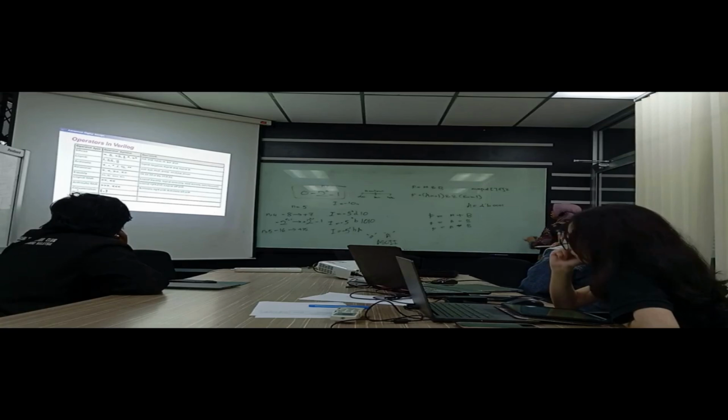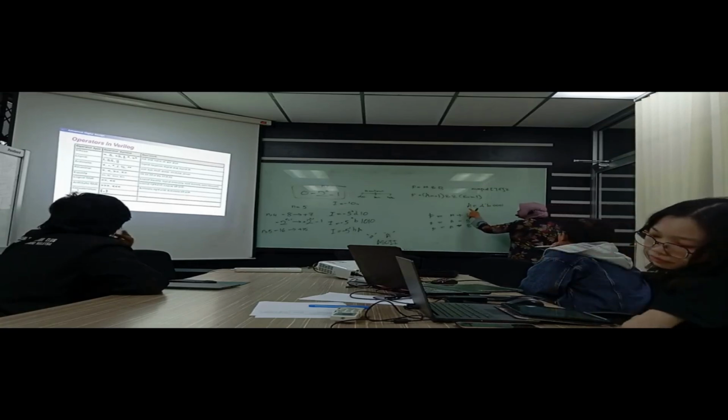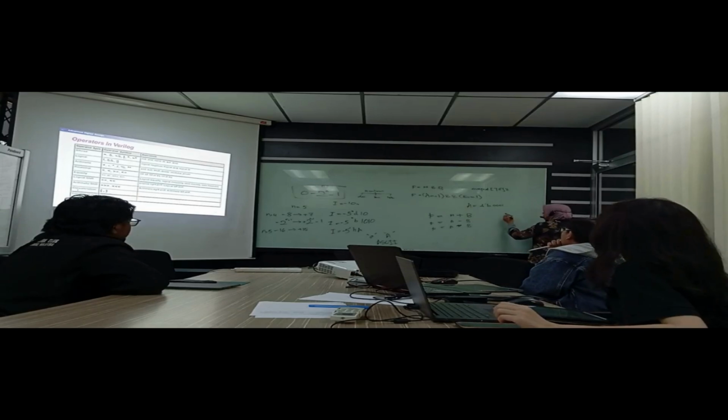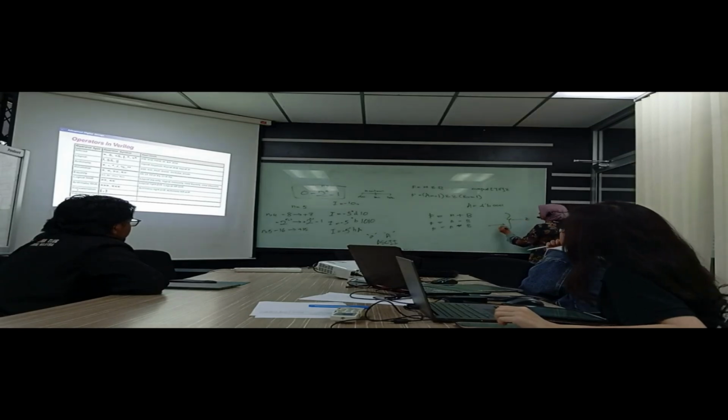And then you just want to wire A to Z. So what happens now in the drawing? This is your Z, and this is your A, 4 bit. Z is 8 bit, but A is 4 bit. So what happened? You have to concatenate.